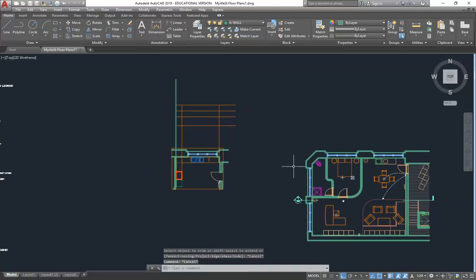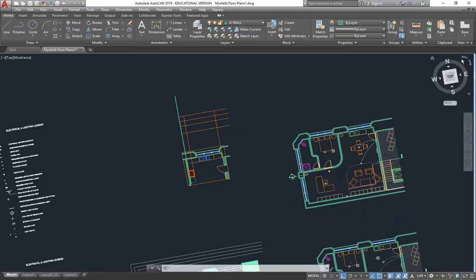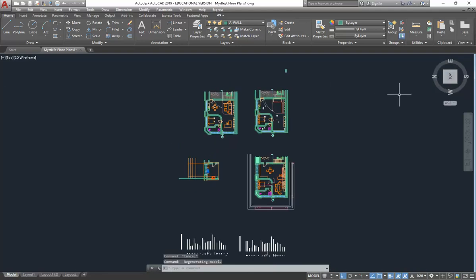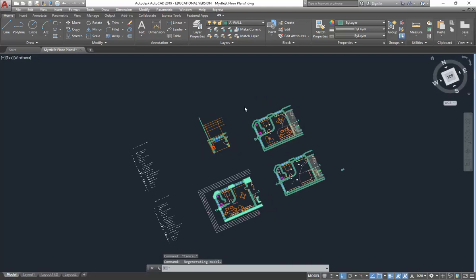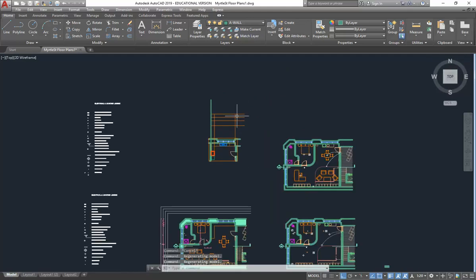So if you want to project off left and right and down, as well as up, that's an option if you're comfortable rotating the view using the little curved arrows there. You can do that, but just remember, it probably is the most efficient way with a set of joinery drawings, but if you're going to work that way, then you need to rotate the view in the viewport later. But as long as you're comfortable with that, and also remember that copied viewports don't work as well, and I'll show you why in a second, then you'll be okay.